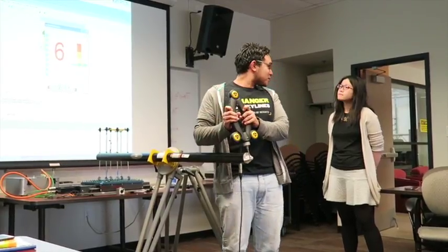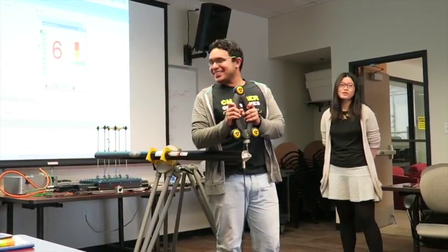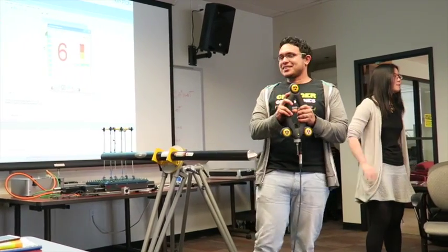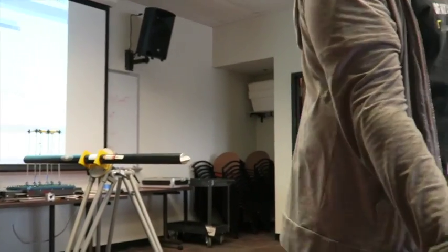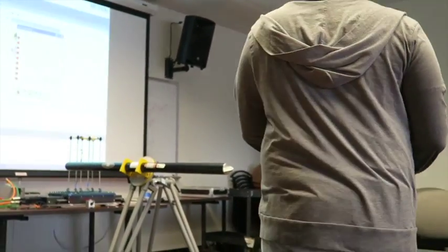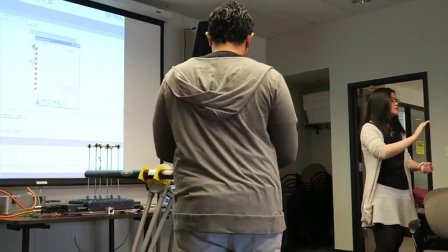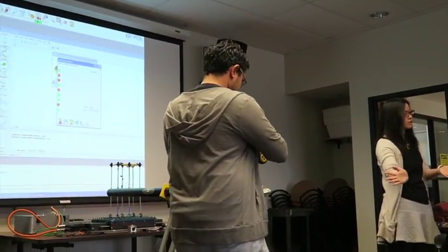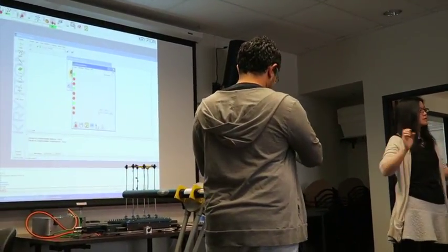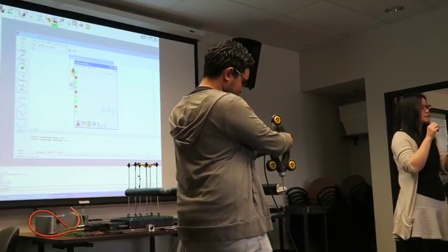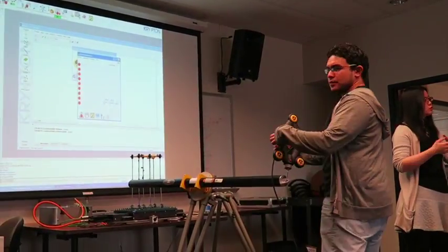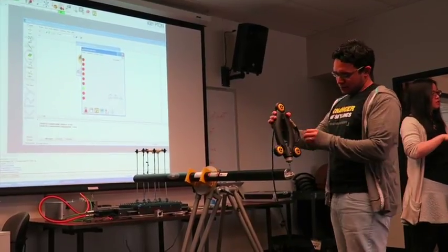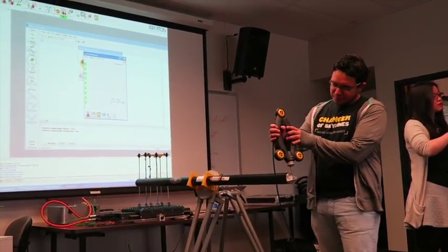What is the number? 0.06, right? Yeah. The suggested number is 0.06 millimeter for the last part, because it's easy, because the range for the left and right, back and forth, they are broad. And at the last, the criterion should be the error bar on the position. So that requires you to move the probe.